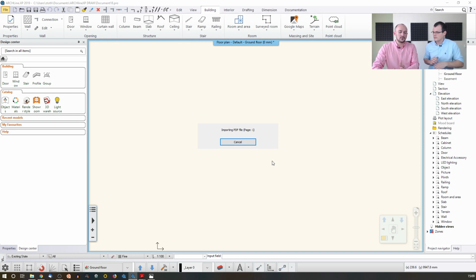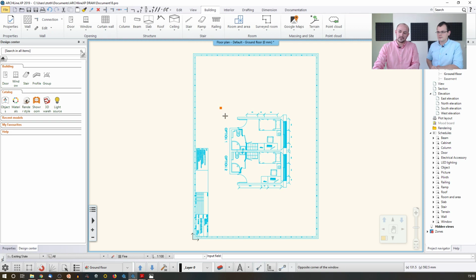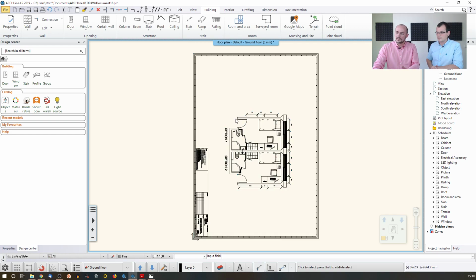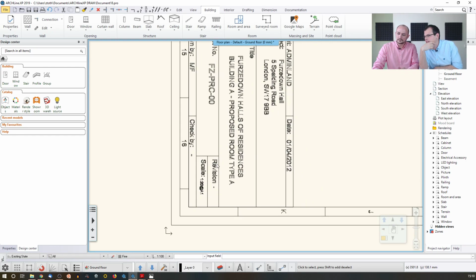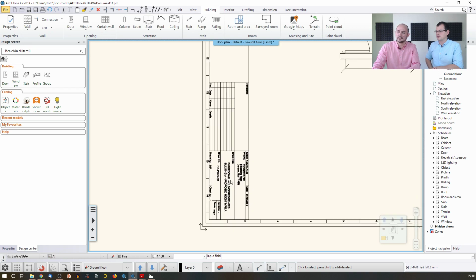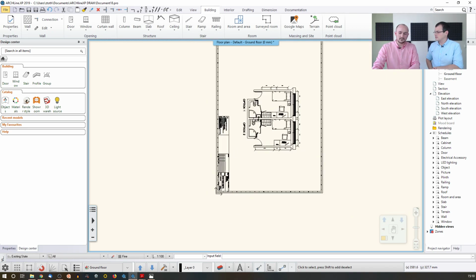And then the first step, always when you import something from whichever source you have when it's a drawing, you should consider that it might not be in the correct scale for you. It was perhaps correctly scaled in the source software, but it's not necessarily correctly scaled when you open it. So here actually we have information of how it was scaled. Yes, it's 1 to 20, I think. We could actually rotate it, but it's not that important. So it's about 1 to 20 or something was the original value.